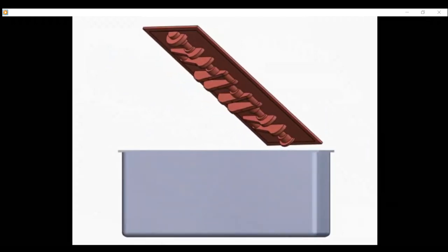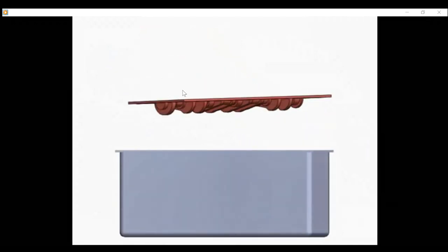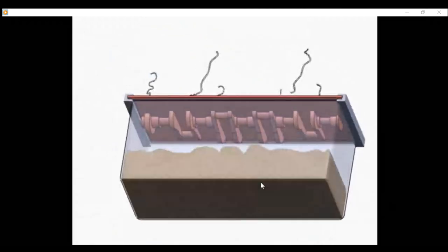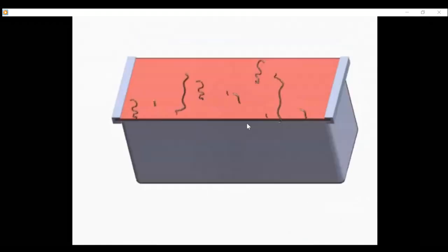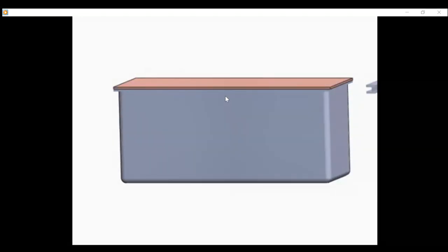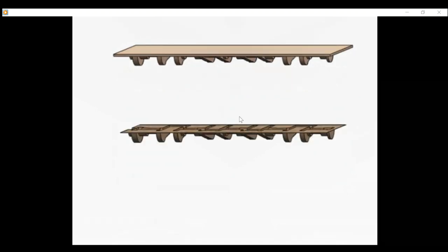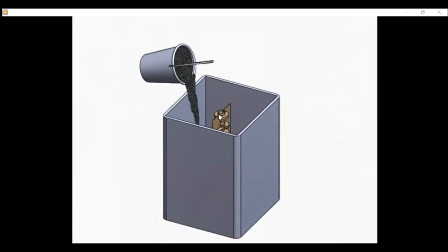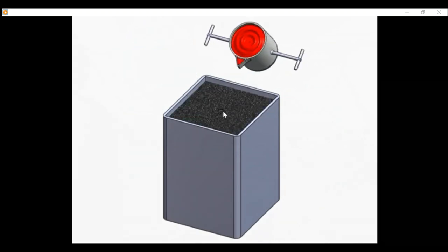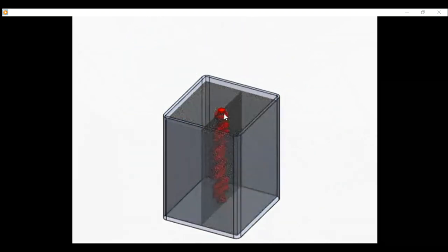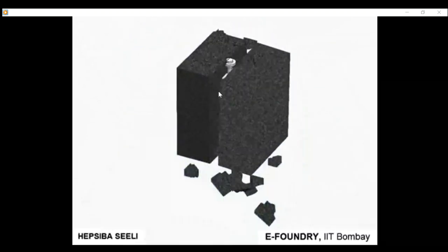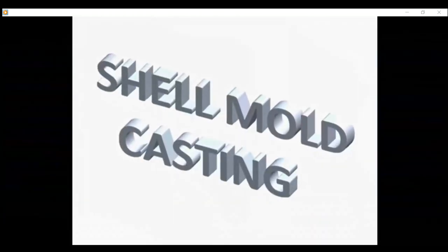Can you see the video? Right. This is the shell. Heated. We heat it. This is the sand. Then we invert it to totally cover, and then invert again after a while. Then you get this one covered with this one. You put it in a furnace, and when it becomes dry, you bring a box and put it here, assemble, and put sand. This is ordinary sand. Then you put liquid in the shell. Then you open this one, finish. Then you take this one, you destroy it. Then you obtain the part made of metal, as you can see.